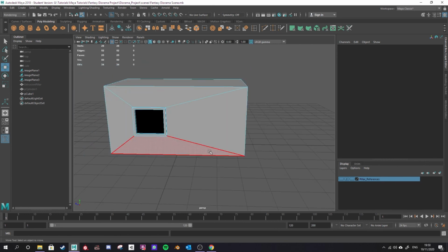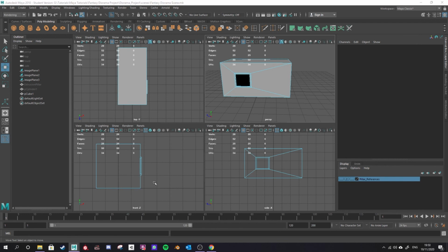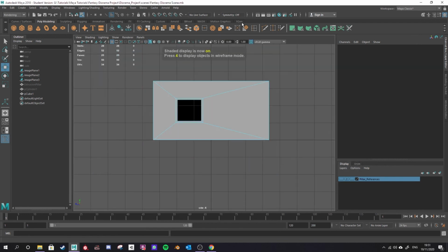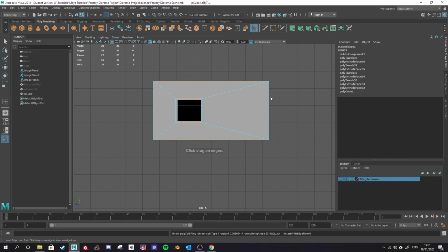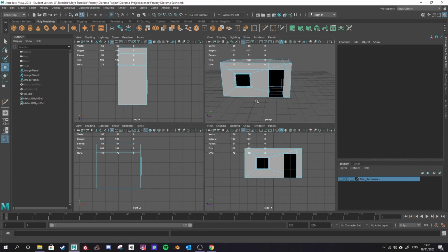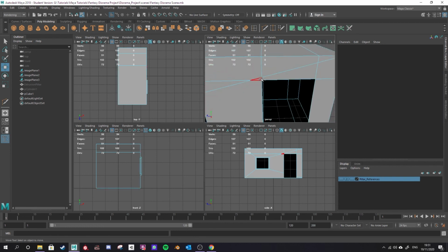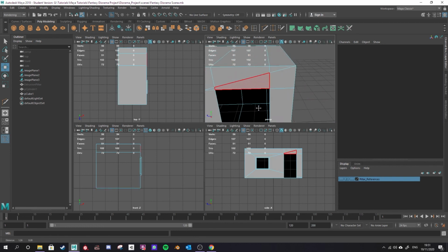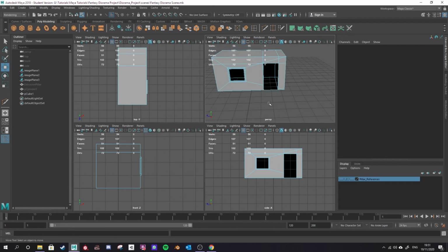Now the problem is going to be here. I need to get a door in here, and I've got these edges that are stretching the whole way to the corners of the house. It's going to create triangles, so even if I go into the side mode, and I use that multi-cut tool technique that I showed you, because if I use the insert edge loop, the edge loops are going to go all wonky because of the way these edges are. So if I use my multi-cut tool, I could technically just multi-cut and cut down through, and then cut through here to create this doorway. Okay, and then I can extrude that if I wanted to make edges or delete or whatever. But that has created a whole bunch of problems for me here. I've got a triangle here, I've got a quad, I've got a triangle up here, triangle here. So really not ideal.